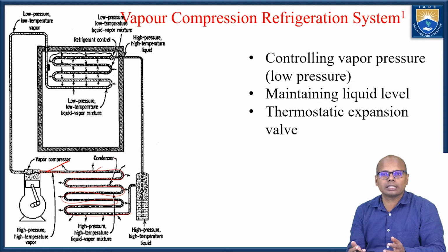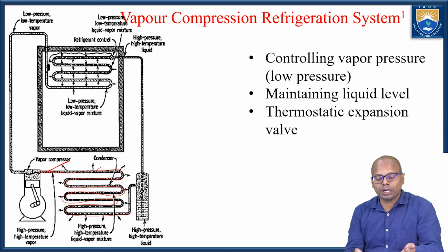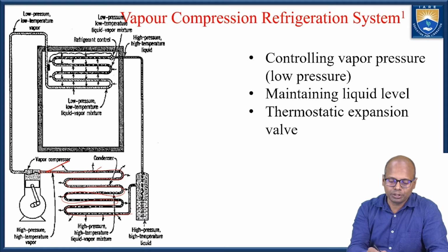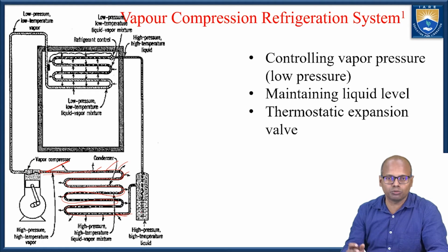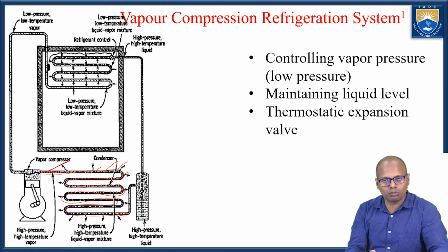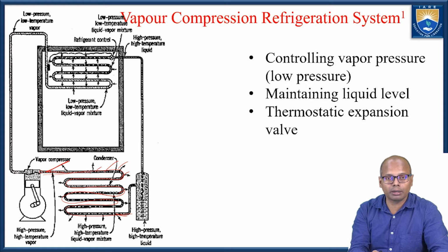Why are we calling it a condenser? We are taking the heat from the vapor and making the vapor condense into liquid form. Here vapor is coming and heat is being removed. We blow a fan or pass some cold water so that the vapor is condensed into liquid, and that liquid is collected in this tank.